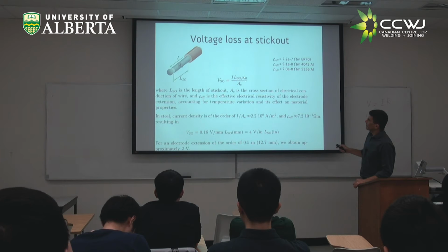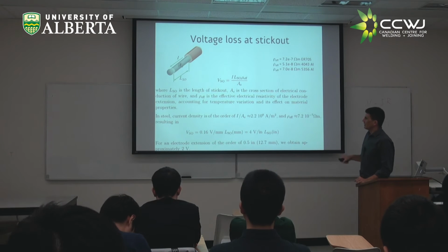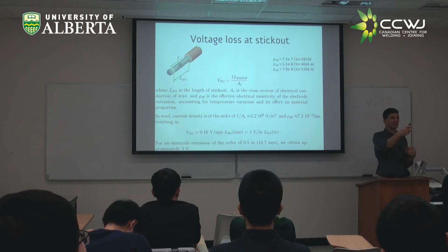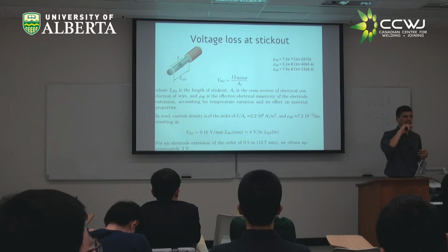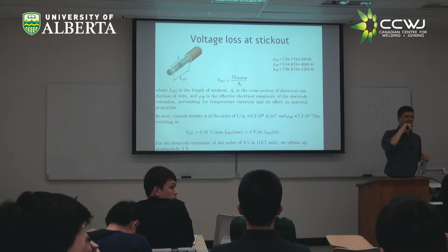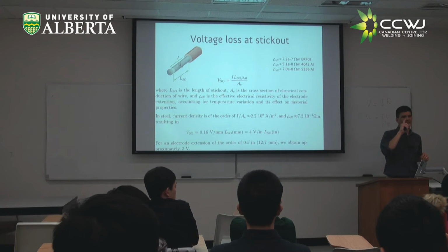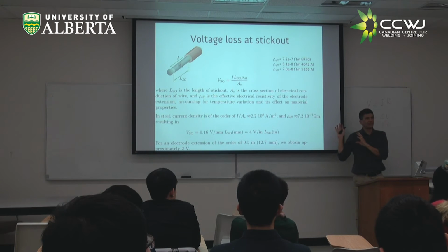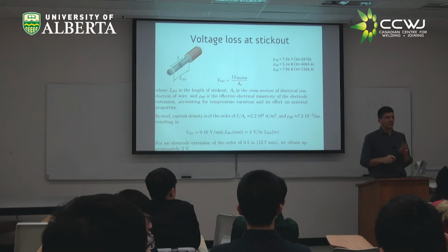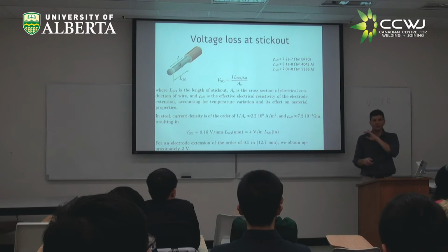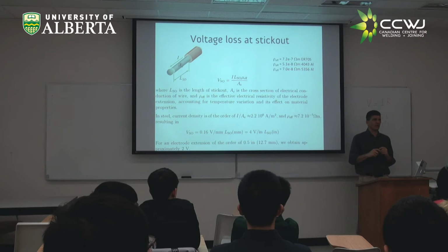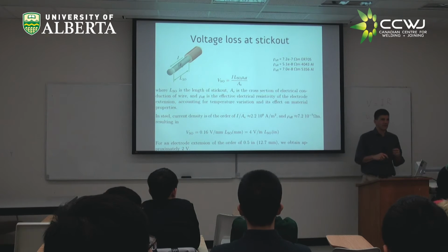But the effective resistivity. So they give you the effective resistivity, but they don't give you the reactance? Okay, let me tell you something. I give you a resistivity because nobody else does. So you have the resistivity tabulated. The reactance doesn't depend on the material, right? Because it's an electromagnetic thing. I will give you a formula for that, but I already gave you a formula, right? But we can synthesize it more or less for reactance too. I have a slide later on that.